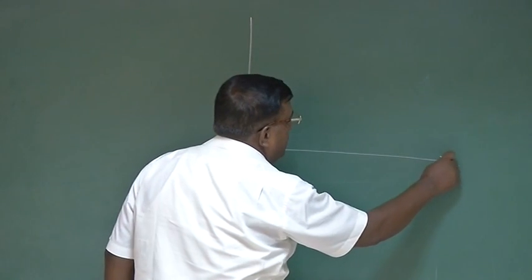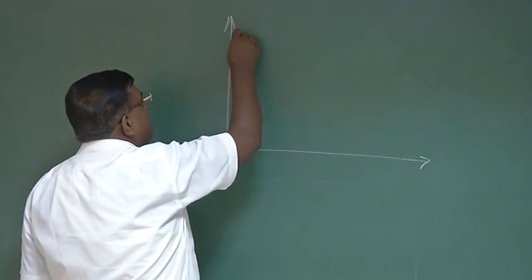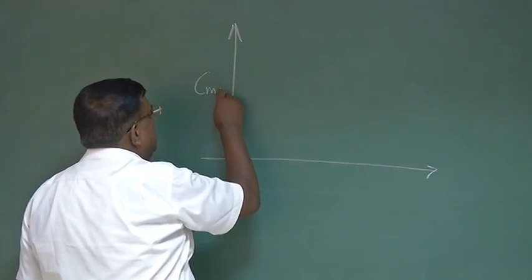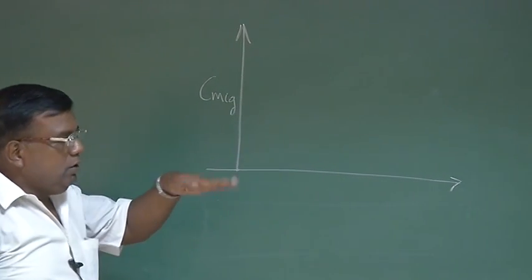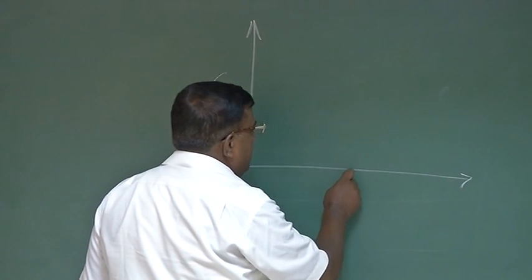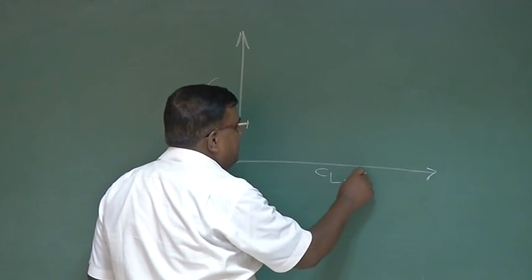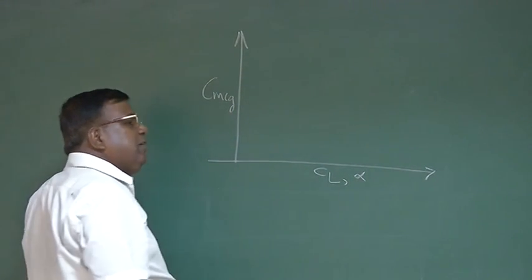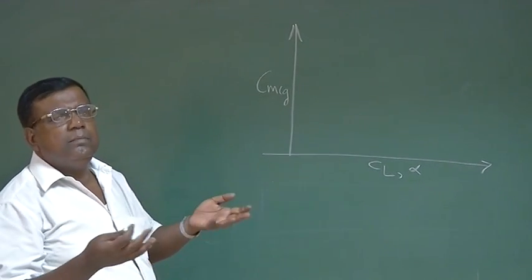if I am talking about longitudinal stability, that is angular motion in the vertical plane, we have seen Cm versus Cl or Cm versus alpha. By now we know Cl and alpha are related through some scalar term.